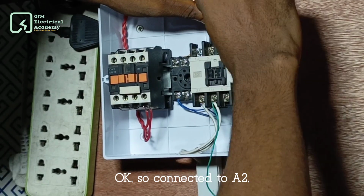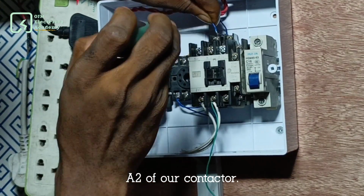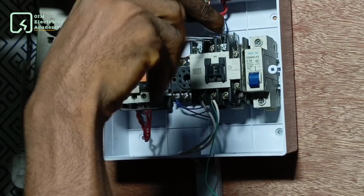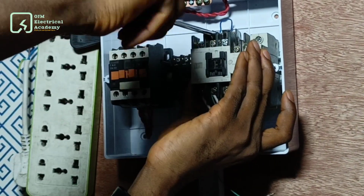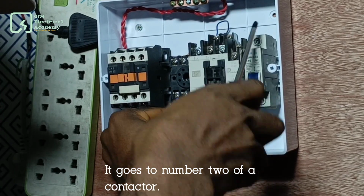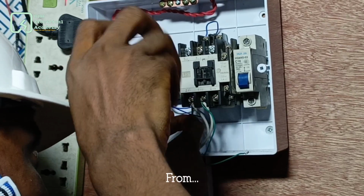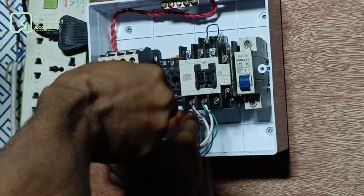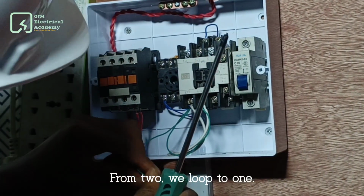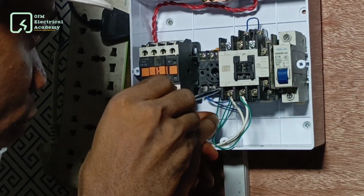So connect it to A2 of our contactor. Okay, so from our A1, it goes to number 2 of our contactor. From our lines, we loop from 2, we loop to 1. So in this case, 2 to 1.